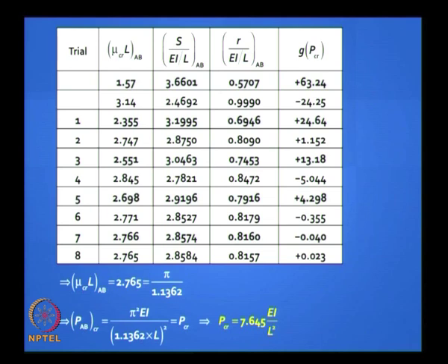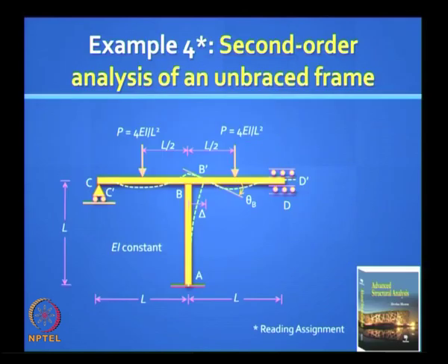Check, did you get a value of Ke between 1 and 2? Yeah, you did. The fact that it is close to 1 suggests that the beam is pretty flexible. Okay, the highest it can go is 2. You can do one more problem, we will not do it. Second order effects for the same structure, once you have got the P critical, it is done in the book.